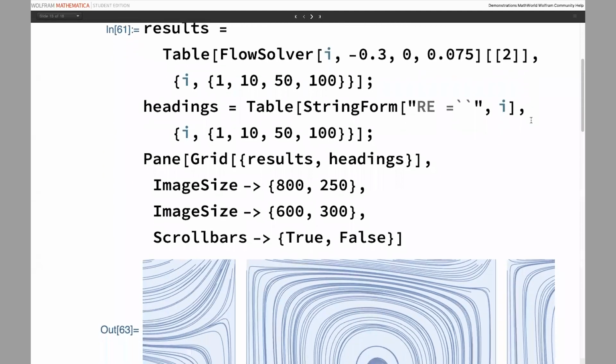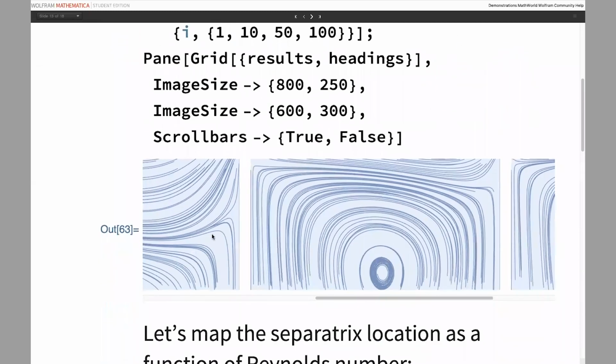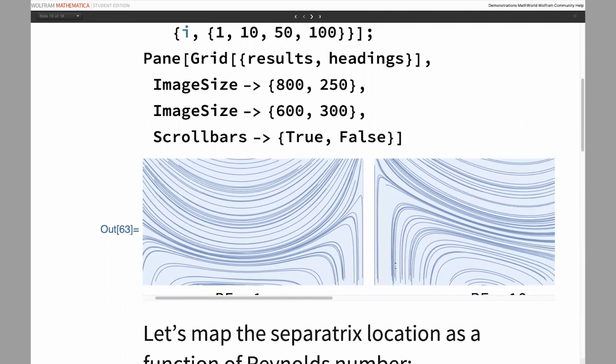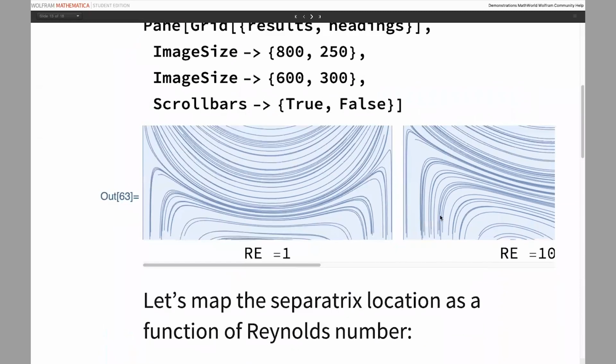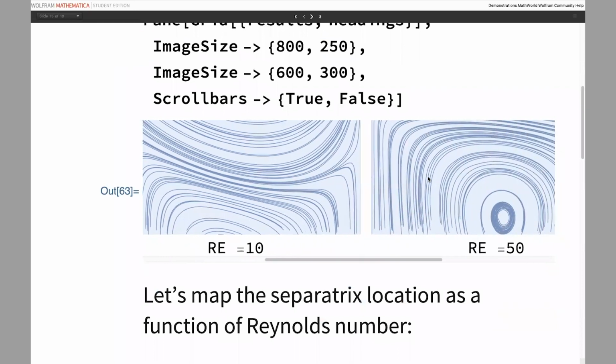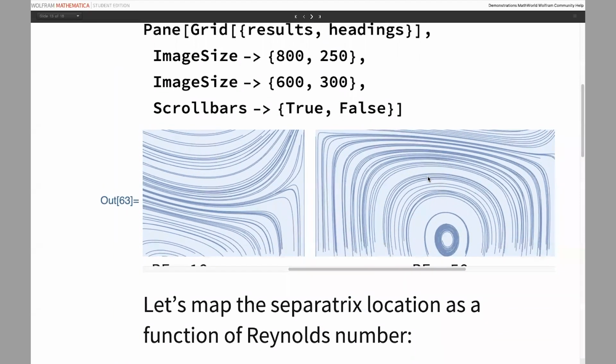So if we, for instance, instead of just looking at that single Reynolds number, look at Reynolds numbers ranging across that whole range of laminar flow, which is when we have that nice smooth flow without any turbulence, we see substantial movement of that separatrix that you can illustrate with a StreamPlot. So here we have a Reynolds number of 1. We increase our order of magnitude by 1. We multiply that by 5. And you see that the separatrix is almost now at that geometric boundary of the pore space.